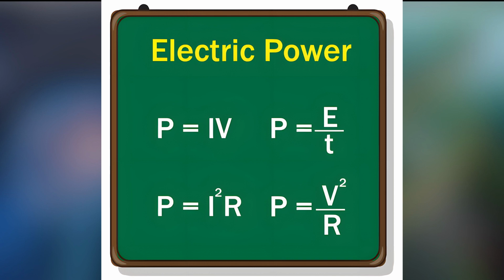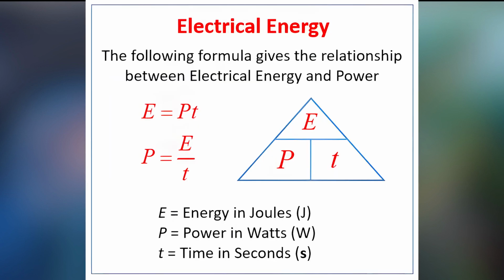It's measured in a unit called watts, which is joules per second. Joules are a measurement of energy, joules per second is a watt. So it's a rate of transformation of energy. You've probably heard of a kilowatt hour, or maybe a megawatt hour. Kilowatt hours are generally used to describe the amount of electricity that a business or a household has used in a month or a week or however often you pay your electricity bills. This is, in my view, a rather odd unit because, remember, a watt is just a joule per second. So if you're using a watt, it means every second you're using a joule of energy.